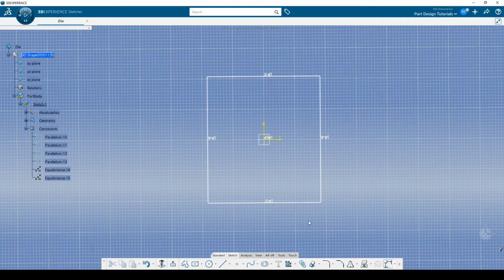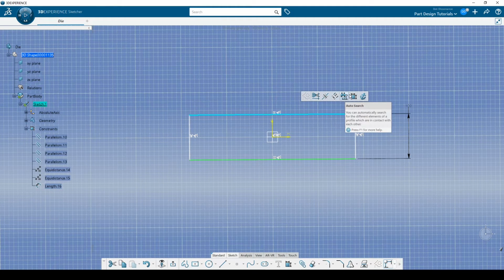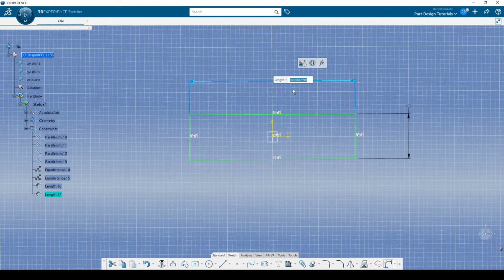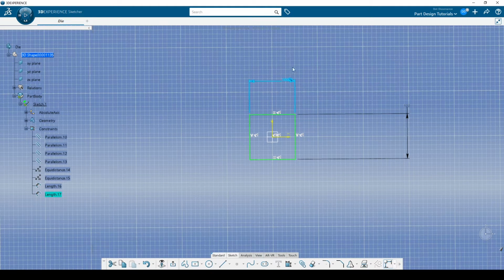So if I want to do the same thing all over again for review, we could click on this, a contextual menu comes out here. I can pick constraint. I could click here like this. I can make it 100. Zoom in a touch, pick this one right here, contextual menu, click that, pick this, and I can hit enter and then double click it, because for some reason there's some kind of a glitch going on that I can't hit equals in that little window, but I can do it right here like so. Okay, so now that's 100 by 100 and that's it. It's already green, you see? It's already ISO constrained. So that helped a ton by just using the centered rectangle.